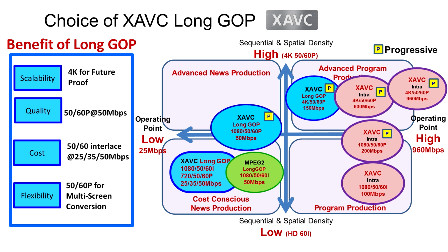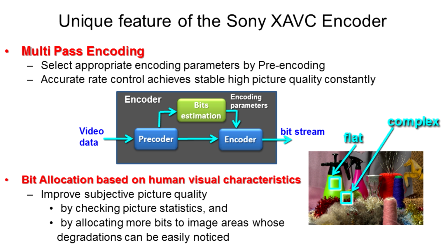The 600 megabits per second intra-frame that XAVC demonstrated in today's F5 and F55 cameras can be alleviated by reducing the data rate to 150 megabits using long GOP. That will enhance the duration time in the recording in our memories. And also, long GOP implementation of XAVC can be used to create proxy videos at very low data rates, which are ideal for wireless transmissions and streaming.